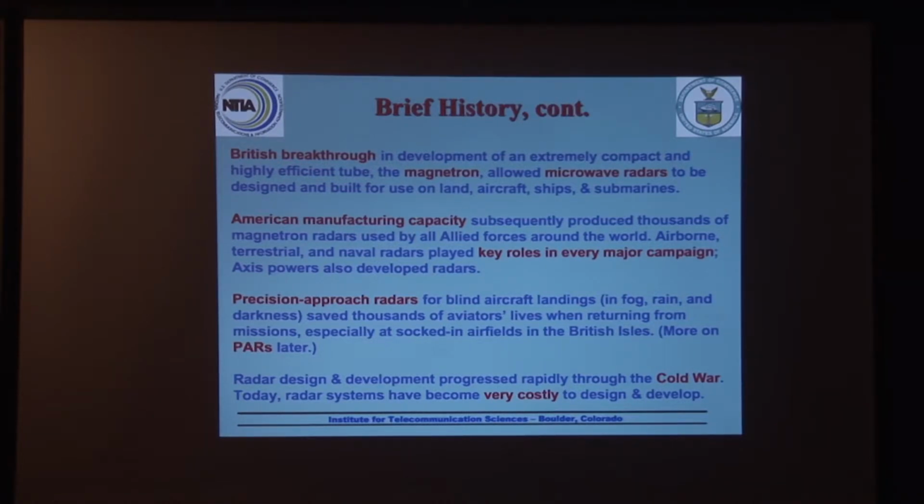If you're going to form a directional beam, you have to build an antenna that's substantially larger in diameter than the wavelength that you're trying to form with the beam. And if the antenna has to be fairly small, then the wavelength has to be even smaller, which means you have to work at pretty high frequencies. As it turns out, you have to work at microwave frequencies.